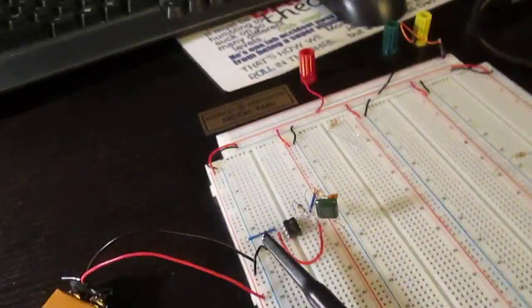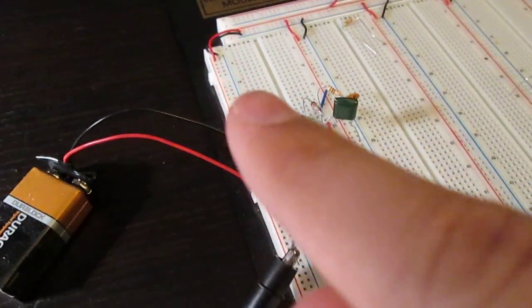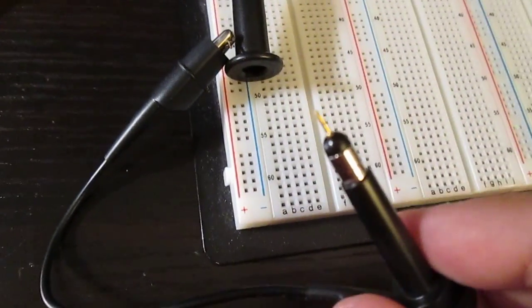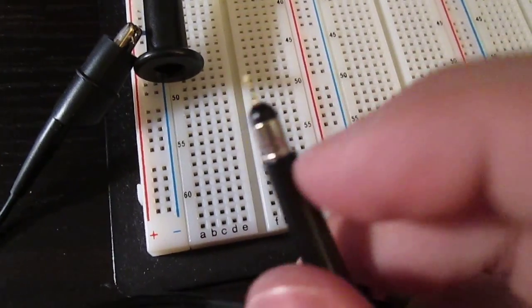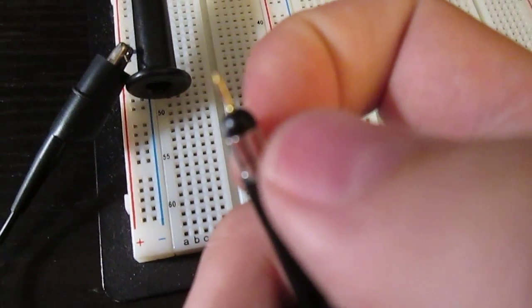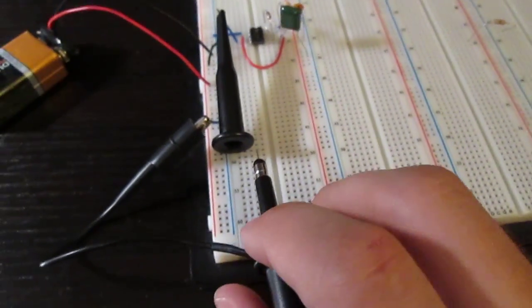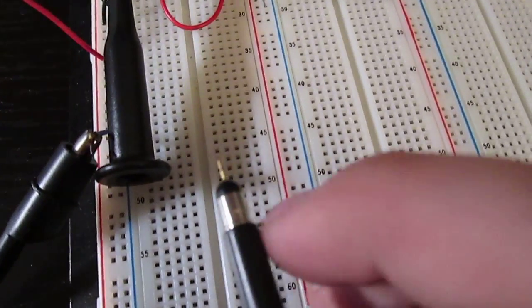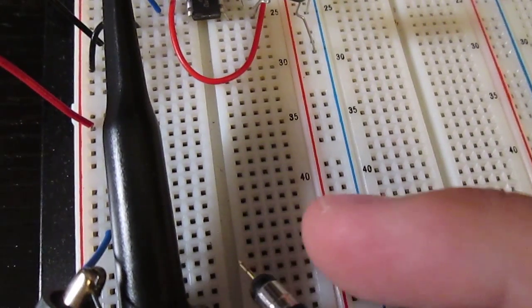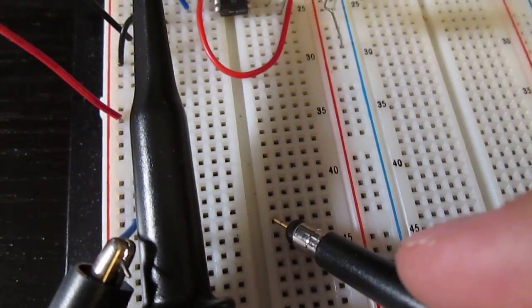In most industry applications, you're going to have a little poker instead of the clip, which is nice for proto boards, like what I've got. You're probably going to have a little puncture, like if you take this off. See, it's going to look just like that, and then you're going to have what's called a ground spring, which is a tightly wound spring that sits on top of this and comes out just a little bit and goes forward. So when you're probing your signal, because on circuit boards you have your signals, and then you have grounds next to those signals with high speed cases, you probe the signal that you want, and first you get the ground with the spring, which will be on here, and you put it at the ground via, and then you poke the signal that you want.